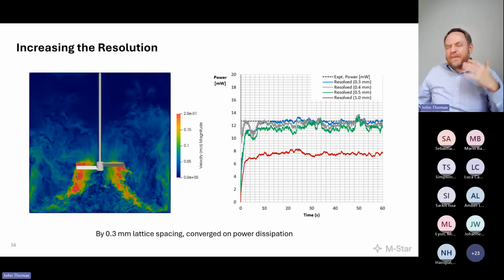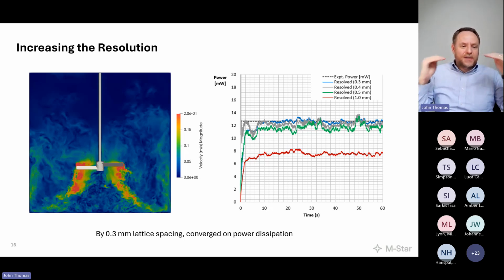And what's unique about that 0.3 millimeter length scale? Why did they get their 0.3? That was the Kolmogorov scale, right? I spoke to it and I was like, these are squiggly lines. But at the end of the day, 0.3 is a pretty good estimate. But that's why I converged there. Why did we get to the point where we saw all energy dissipation around a resolution of 0.3? Because at that point, we completed the spectrum.